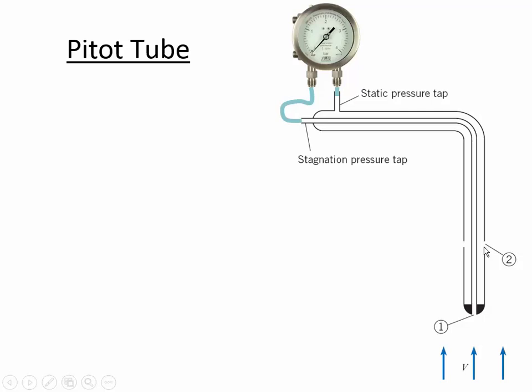And so this is a cross-sectional view, but what they're saying is that there is an opening on either side of it, and the entire area that's surrounding that center tube is where the pressure is lower, and so we have another opening somewhere outside. This pitot tube is basically designed to carry two different pressures to wherever the gauge is: the pressure that's related to intercepting the streamline and the pressure that's related to having the streamline go past it without having the velocity exchanged into extra pressure.